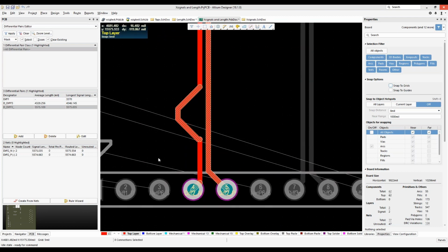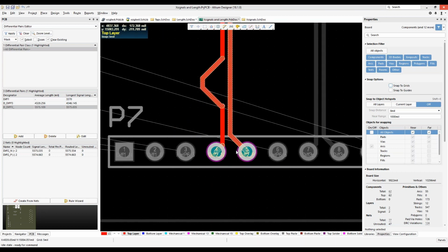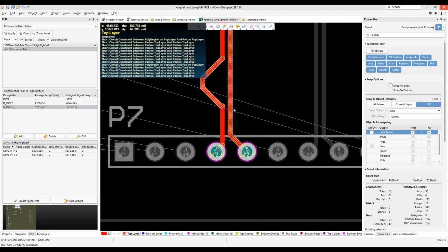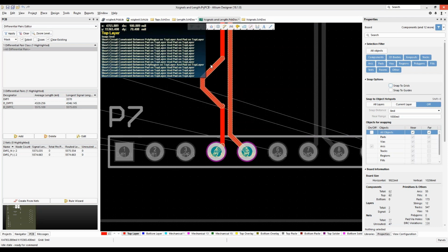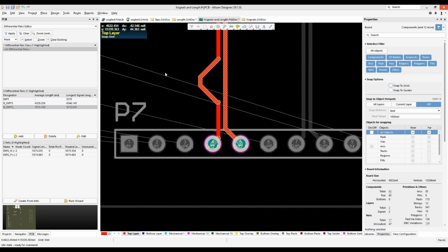The last thing I'll mention before I turn it over to Tom is that we have it a little bit easier here because these both came off at the same time. If you're going through a pin grid array and you've got a little bit of choppiness, you want to correct that match length tuning from the very get-go. You don't want these two signals to travel separately through the entire line.